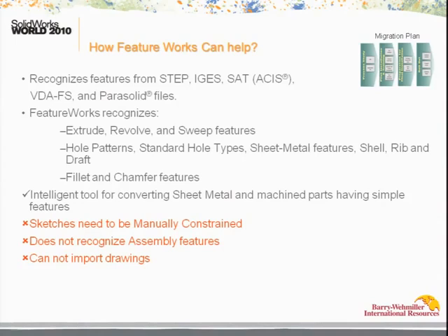In our experience, what we have found out is models and assemblies which are complex, like your cams, which have a lot of lofts, which have intricate cutouts, or which are sketch-driven and which are based on a pretty complex sketch. For those type of parts, you have to do a manual data translation. There's no other way out.